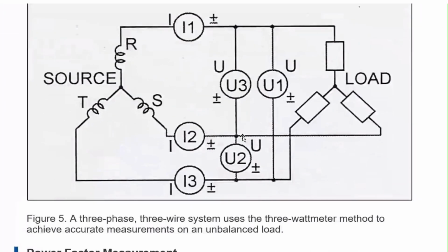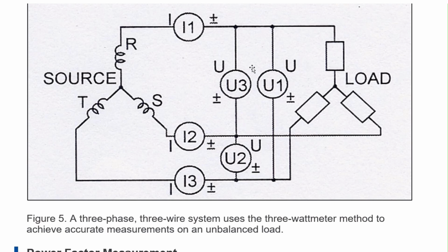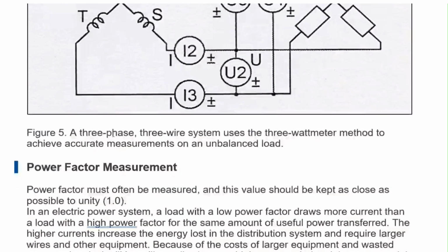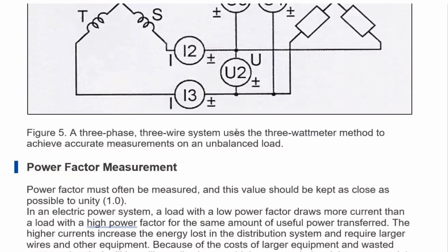So here also, this is a three-phase three-wire system where the connection of 3 wattmeters has been shown. That could also be the situation that we have a three-phase three-wire system and we are employing the 3 wattmeter method to measure the total power consumption of the circuit.